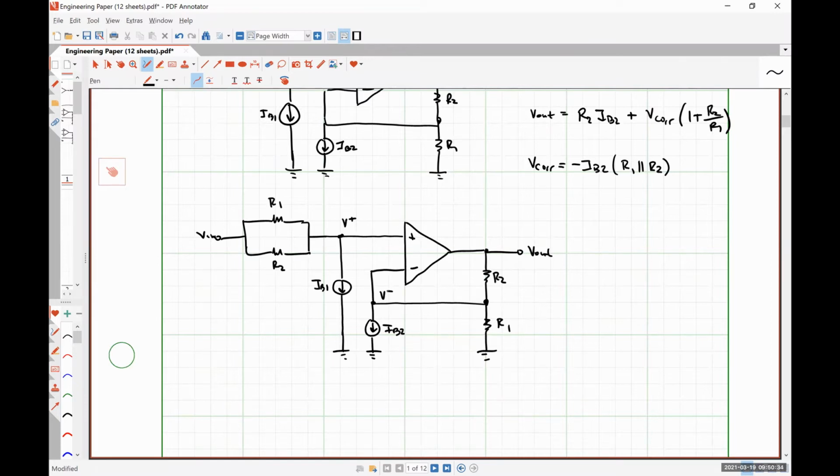So the exact same voltage representations that I used way back in circuits 2. V plus for the voltage at the non-inverting input, V minus for the voltage at the inverting input, and because we're dealing with an ideal amp, they represent the exact same quantity. So, what is that voltage V plus going to be in this circuit?